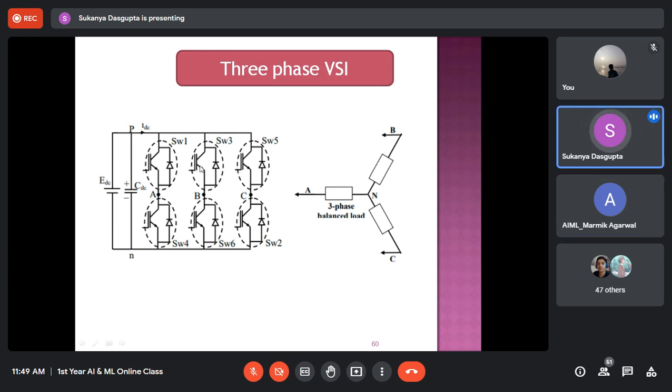See, these two are not working because you will not send any gate signals to these gate terminals at that moment when this one is working, because theoretically no current should flow through these paths, because again it will converge to the starting point, which is the positive DC. So again the input side will be shorted. And SW4 also cannot be operated whenever SW1 is working. So definitely these two switches must be conducting in order to provide the two return paths of this current, one through phase B and one through phase C.